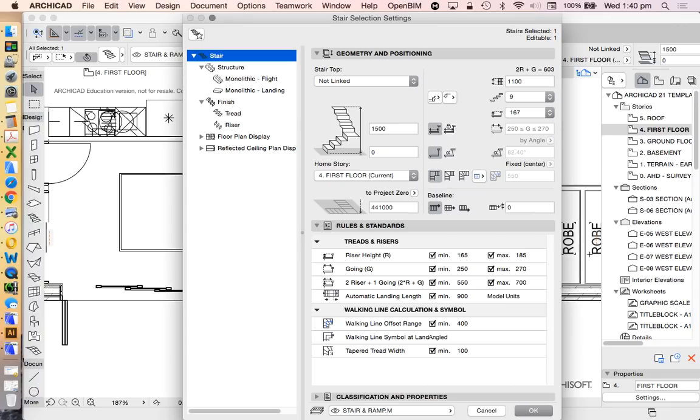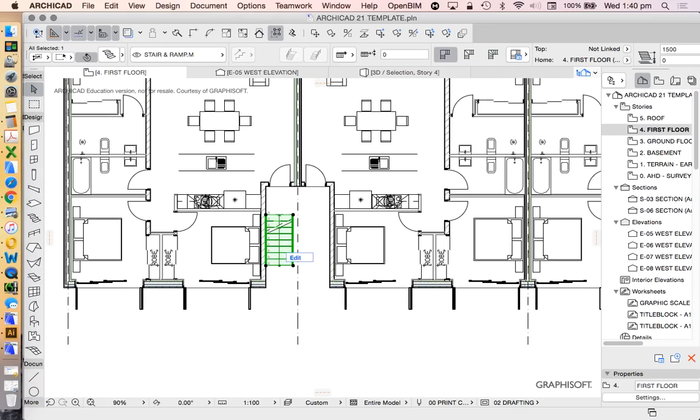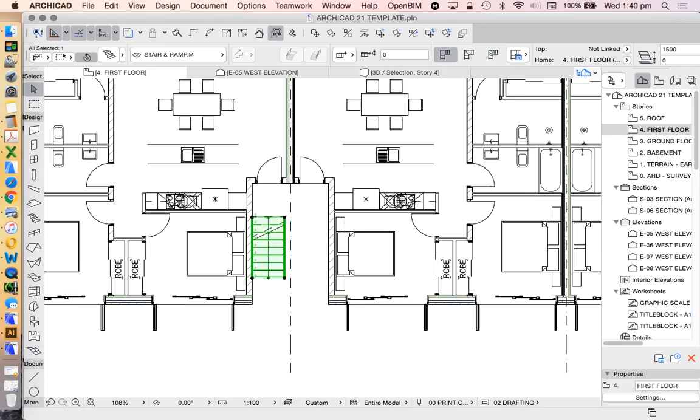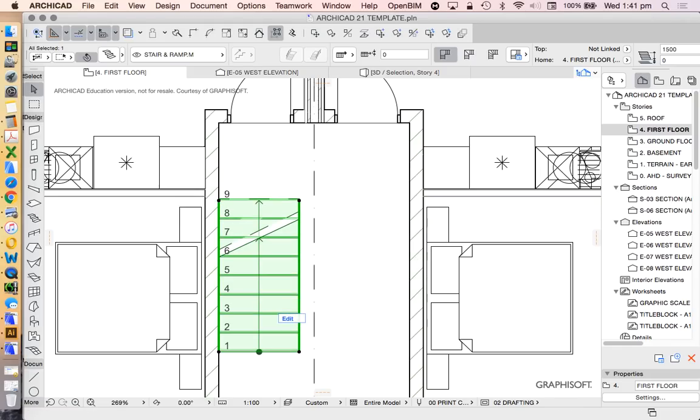Now, therefore, if I'm going to choose one or the other, 270, 250, or anywhere in between, what's going to make that decision for me? Maybe it's based on the space available to me, but realistically, that space is just defined by me anyway. It's based on my design. So I can make that whatever I wanted to. Let's just move it a bit. So let's move it up another 100 millimeters using the drag tool.